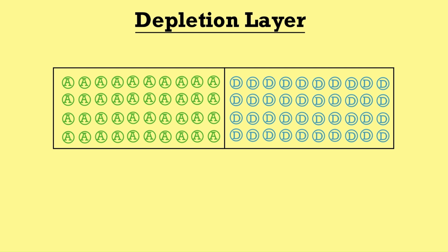The principle and process behind construction of semiconductors requires not only a separate chapter but a separate subject. Processes like etching, crystal growth, lithography, all these are taught in VLSI technology or advanced electronics. Here, we will not go in much depth. You simply assume that the entire semiconductor crystal is of the same semiconductor material. And also, in one side of the semiconductor, P-type impurities are injected and in the other region, N-type impurities are injected. This is called the metallurgical junction.